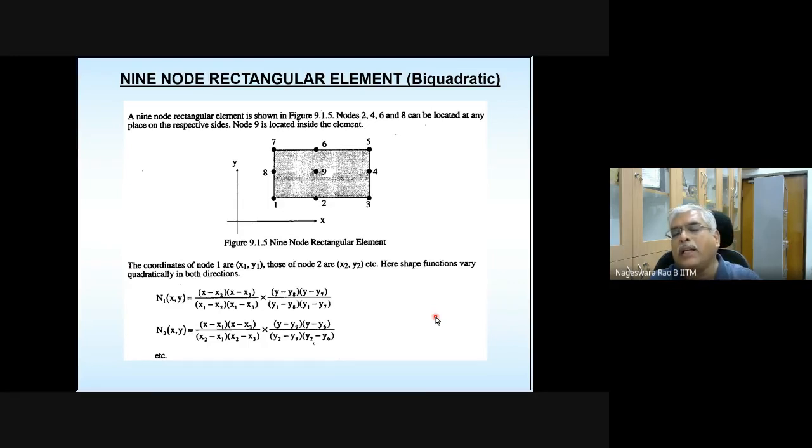So people were trying different methods. Surprisingly, they found the 8 node element, which is the best solution possible, removing this floating node. That's why that 8 node element is called the serendipity element. Once you understand the procedure for deriving the shape functions for the 8 node element, you apply the same concepts for the 5 node element and 7 node element. So they are also serendipity elements.